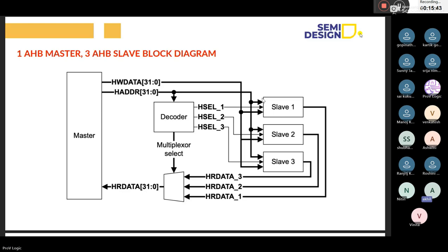When we configure an IP, they will ask which protocol is the interface protocol: AXI, APB. So that means the bridge will be inside this IP, correct? Yes, the bridge will be connected not inside the IP, but between two IPs. On the lower side, suppose an APB protocol is there, the APB will be connected to the lower side IP. APB to bridge will be connected. APB will be inside the IP. Let me draw.